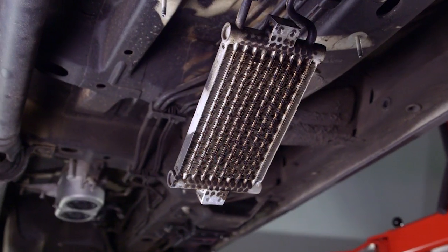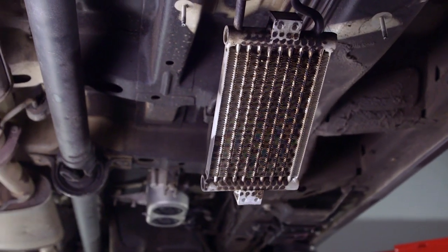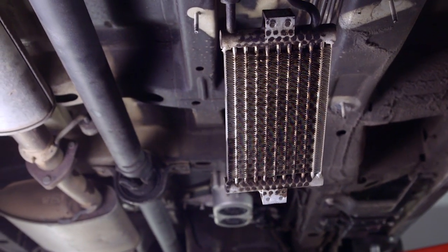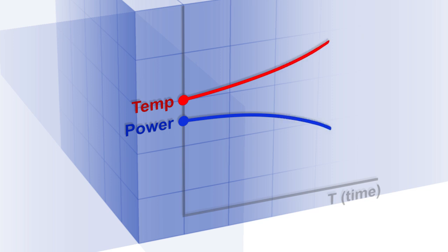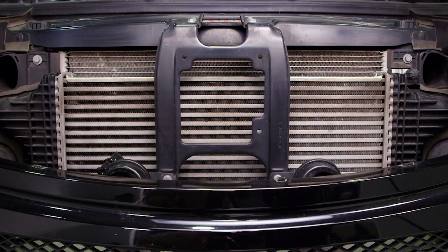A fuel return line is connected to the injectors, rail pressure control valve, pressure limiter, and the high pressure pump. On this vehicle, the return fuel goes through a fuel cooler before going to the tank. As the fuel goes through the injectors, it will increase in temperature. This is caused by the fuel pressure and the temperature of the engine. An increase in diesel fuel temperature will cause a lack of power, so a fuel cooler may be employed to counteract this temperature increase.